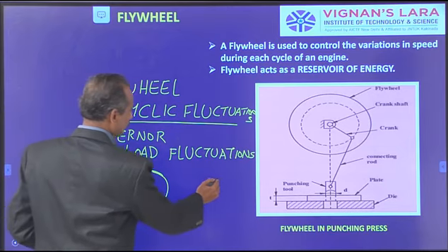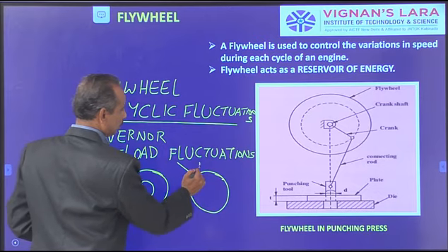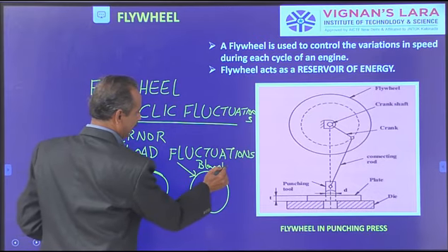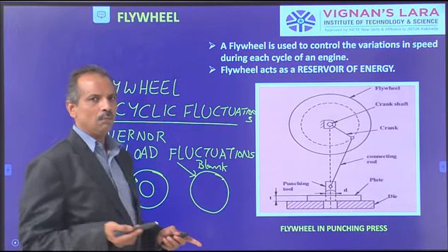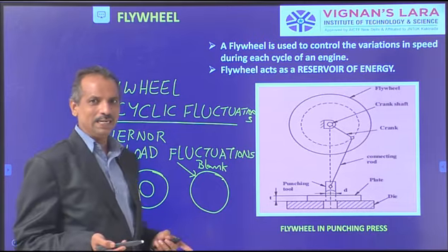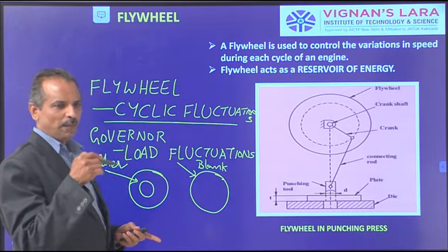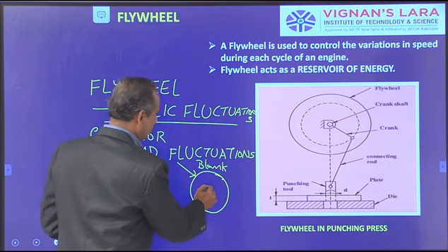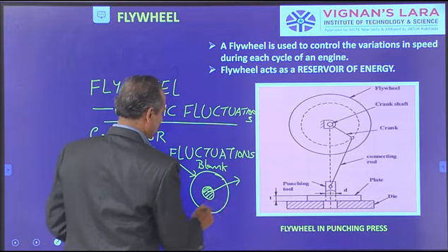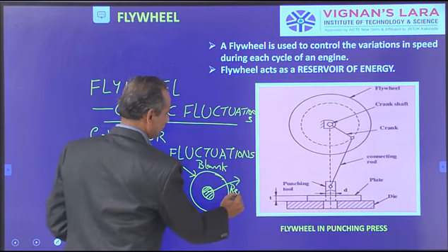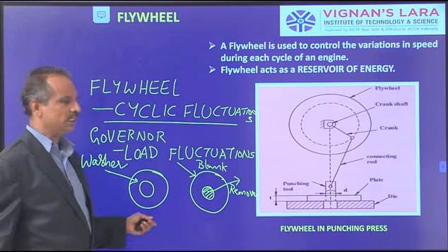So I take a plain blank, and I keep it on a platform or on a table or on a die. Then by piercing with a tool called a punching tool, I remove material from here. Then this is removed, and I get my washer like this.